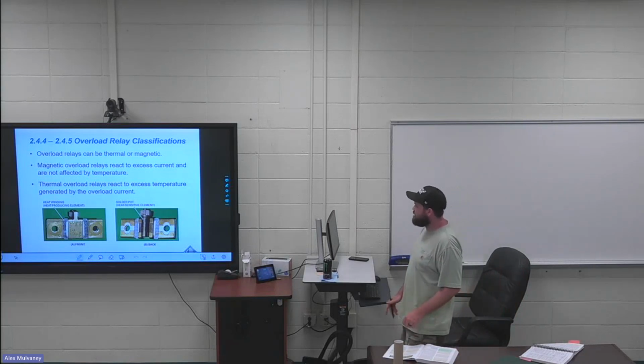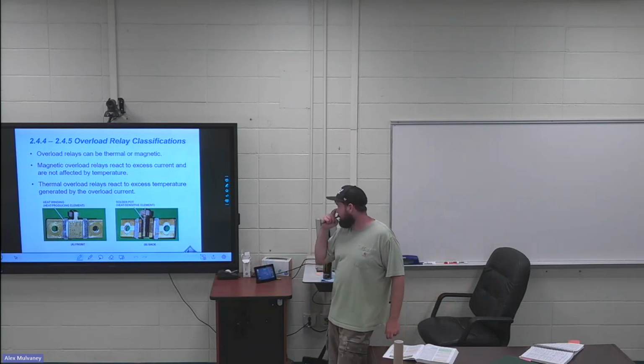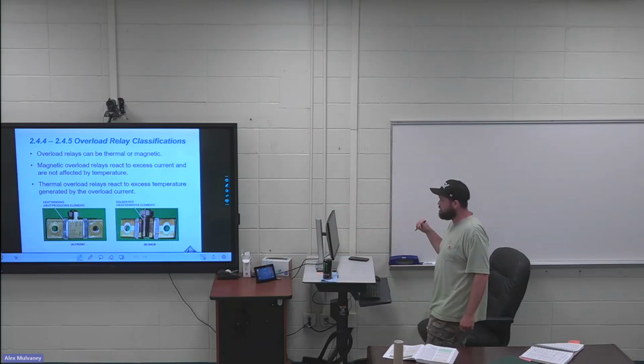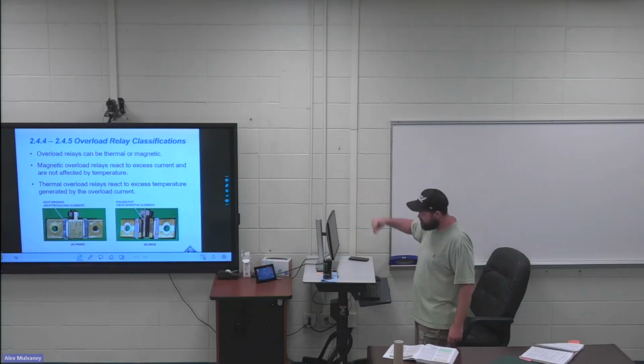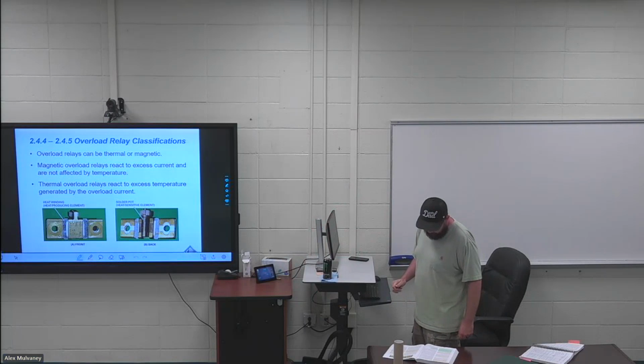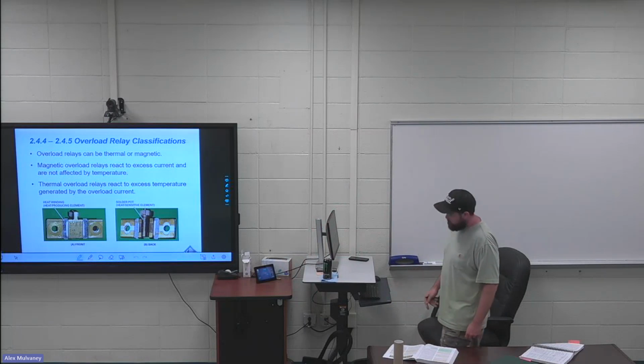So very simple device, but very effective device. That solder inside that pot is going to melt only at a certain temperature. When we hit that temperature, it melts, and you can see that wheel on the side that spins. Asked me to show you all those in the lab. Like we can take those off, and you can see those melting alloy thermal units for these motor starters.